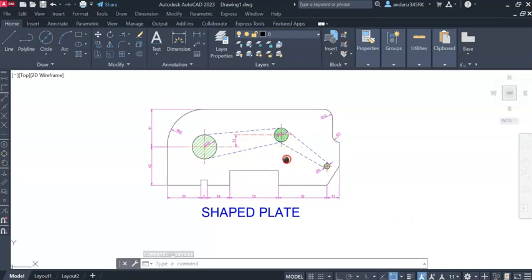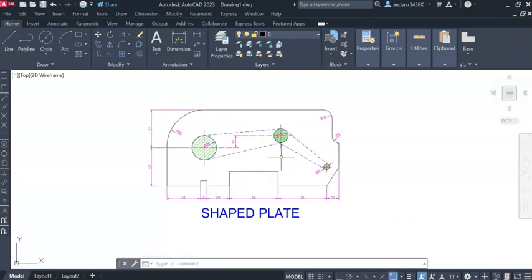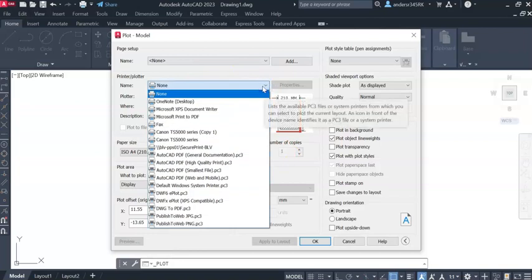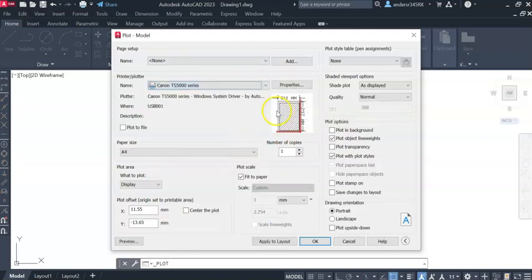Right, people. Then your lecturer tells me that you want to save this as a PDF. You print it. What you do is you print it to a PDF. Okay, right now my drawing is an A4 size drawing, so what I'm going to do is this. I'm going to go to Plotter Manager, sorry. AutoCAD likes to plot, not print. It just calls it the same thing. Right. Give it a plotter name. And my one is going to be this one over here, because I'm at home.